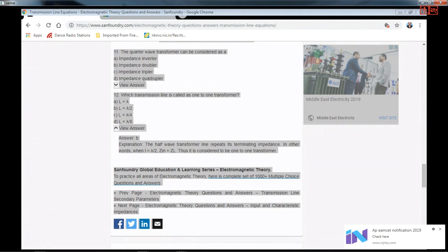Capital gamma, that is the reflection coefficient in complex form, is going to have a range of values of -1 to +1. If it is the magnitude of the reflection coefficient, it is only going to vary between 0 and 1. But most of the times people get confused and they expect the answer only 0 to 1. So please tell them that gamma is going to have -1 to 1 in complex form. If it is only magnitude you are looking for, then it is 0 and 1. Please try to elaborate an answer. Then definitely you will not get into any trouble.